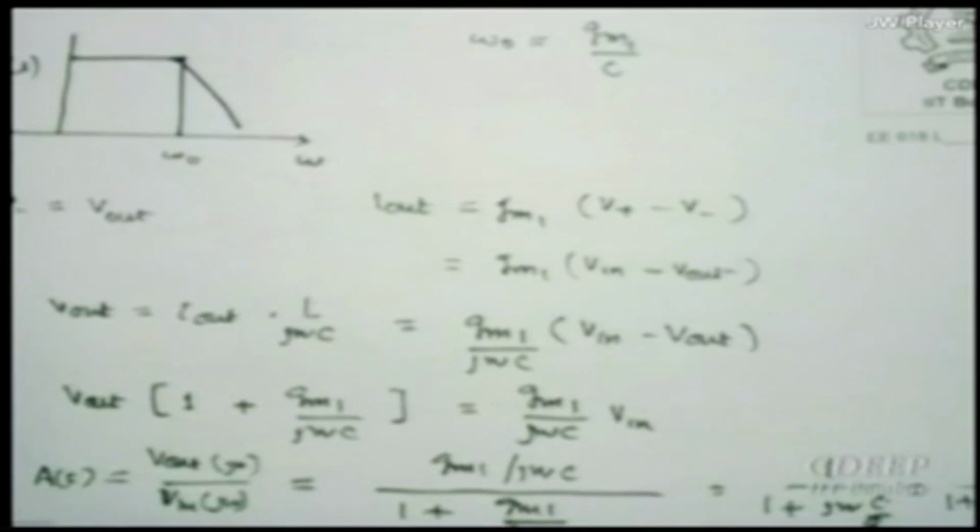Bias current. K of course is fixed once and I cannot change it, maybe 4 at best you may put. That means I should change the bias current. So a low pass filter with variable cutoff is now possible from V control. So I change the V control bias and I have a different cutoff for the low pass. So it's a tunable Gm-C filter, is that correct? It's a tunable Gm-C filter. That is the fun of OTA, that OTA allows you to do such tunability.